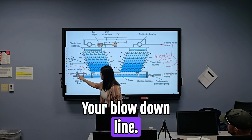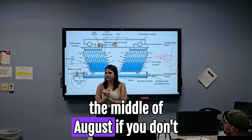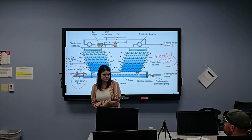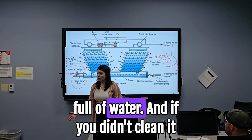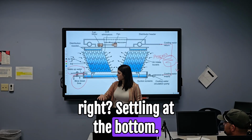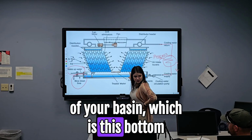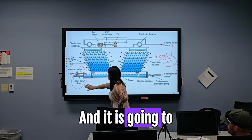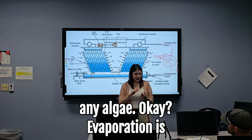Your blowdown line: it's hot and it's wet. Think of a swimming pool in the middle of August if you don't treat it. Algae builds up. Or like, anyone ever have an outside dog? Our outside dogs, they were big Catahoulas or hound dogs, and we had a 5-gallon bucket full of water. If you didn't clean it on the regular, it'd fill up with algae, right? Settling at the bottom. So your blowdown line is going to come off of the lowest point of your basin, this bottom of the tower, and it is going to continuously be open. We're wasting some water, yes, but we're getting rid of the algae.